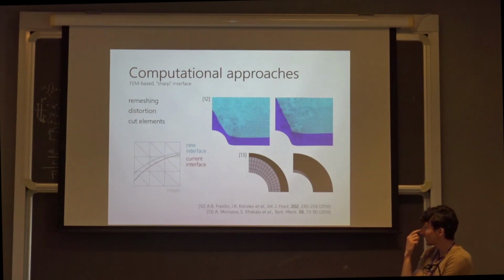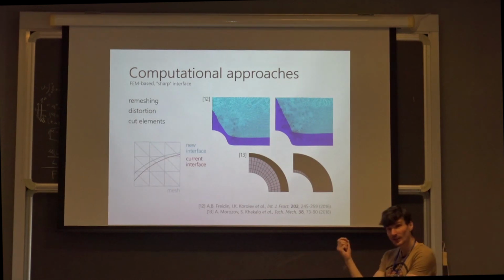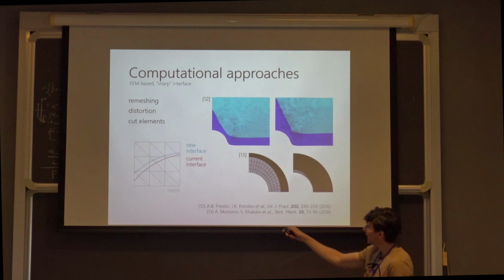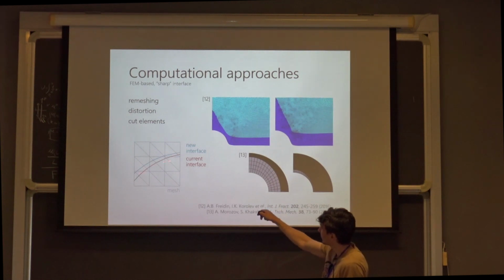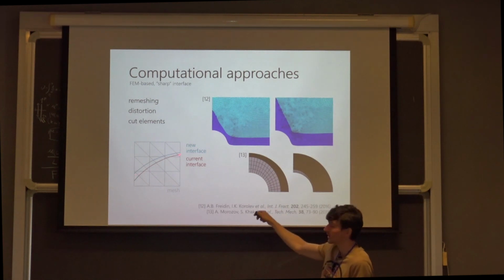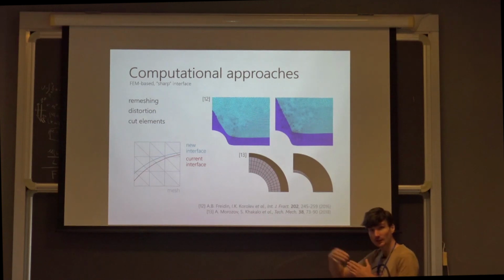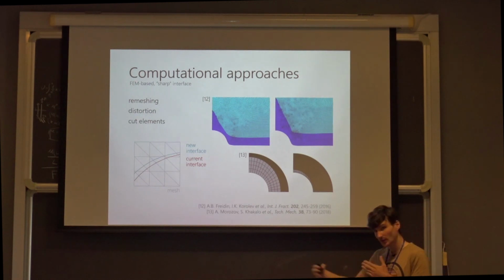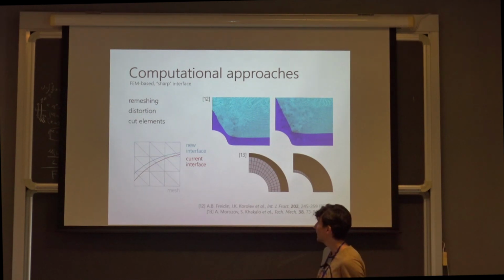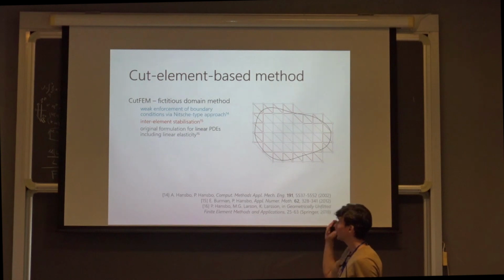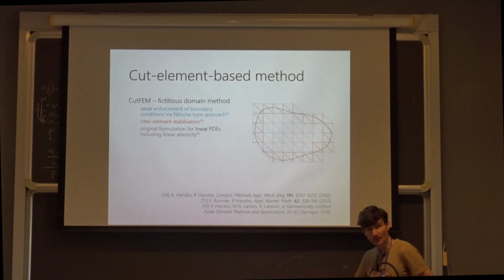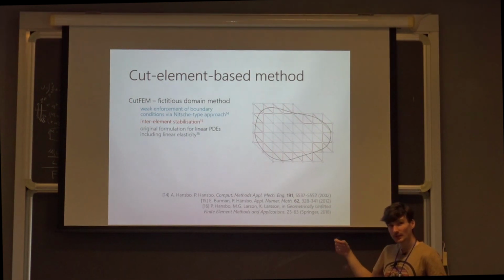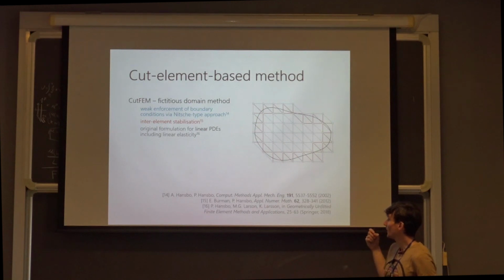And the last option, which is most appealing to me, is when we have the background mesh and the interface which cuts through the elements. In this case, the interface can move independently of the mesh. If you are familiar with the XFEM strategy, it's a similar idea to XFEM, but what we specifically use is the CutFEM method. We spent quite a lot of effort working on this, but I will just show the basic idea.